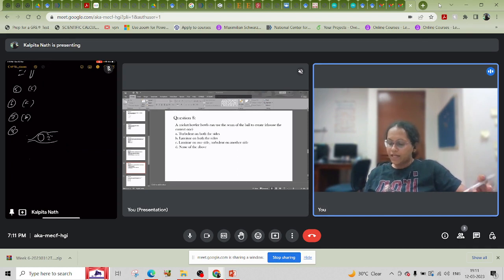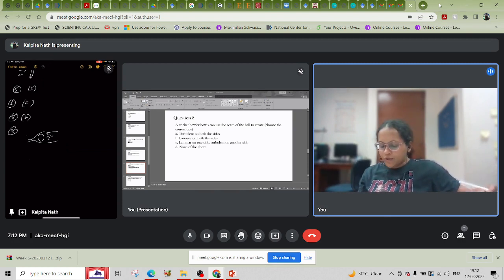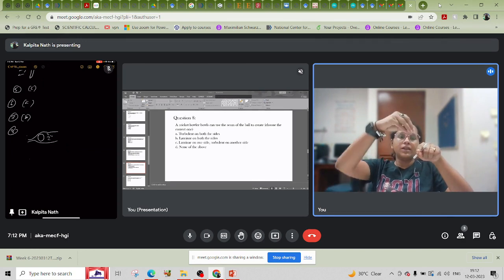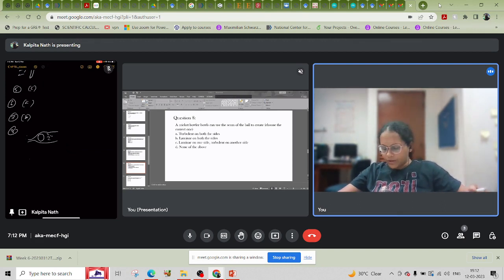However, on a very smooth surface and at nominal speed, a laminar boundary layer can be forced to turn turbulent by tripping it with a disturbance. The disturbance can be in the form of local perturbance or surface roughness, which adds turbulent eddies to the laminar flow. It is similar to putting a finger into a smooth stream of water from a tap. When you open the tap and place your finger in between, the water will flow like this, so eddies are generated here and the pressure will be low here. Small chaotic turbulent motion is generated downstream of the finger location.